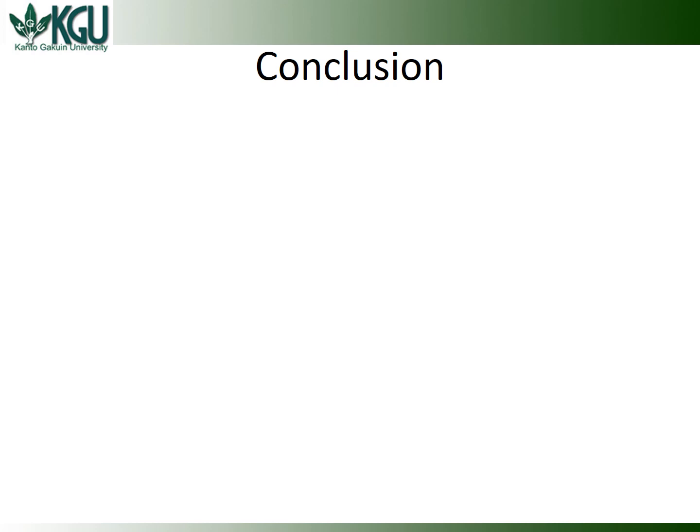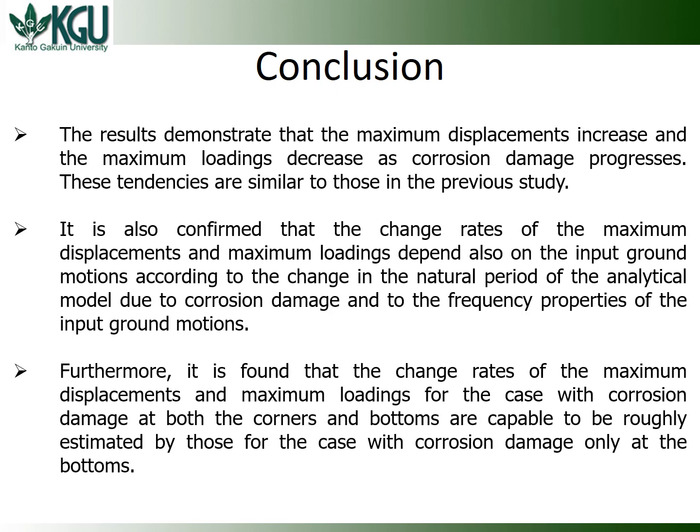Number 2. It is also confirmed that the change rates of the maximum displacements and maximum loadings depend also on the input ground motions according to the change in the natural period of the analytical model due to corrosion damage and to the frequency properties of the input ground motions.